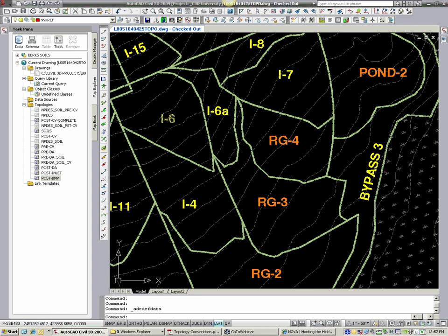So you get into this process-based method of doing stormwater management where you do a preliminary cut, you get everything in, you design it up, and then you come back later once the grading is completely 100% done. You tweak lines so it looks right and everything's actually correct, and just run through that, which probably will only take like 15 minutes. Most likely the tweaks are small enough that your pipe designs won't change, but you'll validate if they need to go up or down. Or your ponds probably won't change, but you'll validate if you need to change some structures out, and then send it out the door.